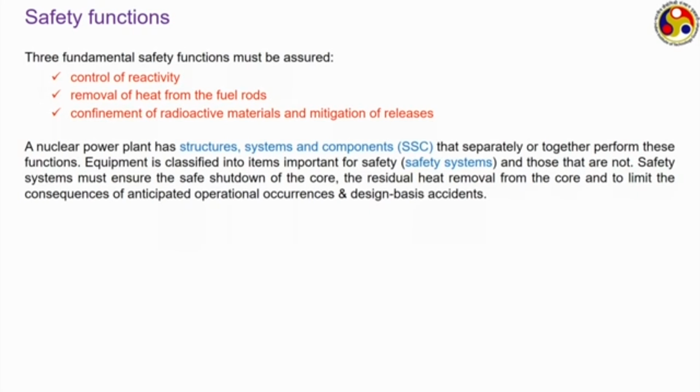Here I would like to quickly mention this residual heat removal. Any amount of heat generated in the reactor needs to be removed, and that is true for a coal based thermal power plant as well, but there, when the coal is burning, we have the energy available and the coolant needs to take that energy, but once the coal has burned, then there is no energy potential available. But that is not true for the nuclear.